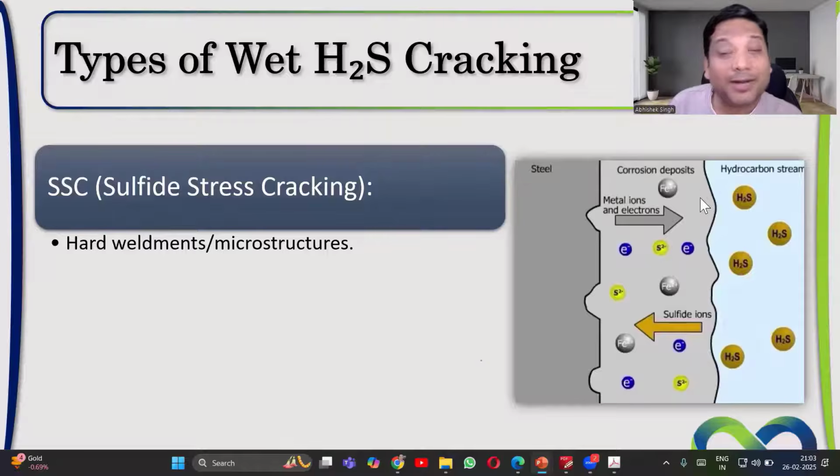Hydrogen being a very, very small ion, it fills the voids which are there in the material. In the structure of that material, there are voids. So hydrogen fills that. By filling that, it makes the material harder and prone to cracking. If the material becomes hard, it will crack. Now, the very interesting point is that